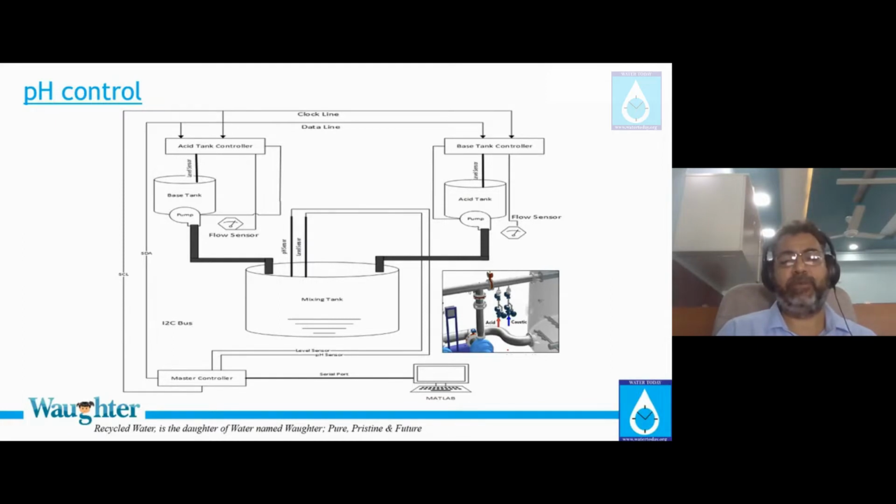You have to take a reading from some point. You have to sense it, and you also have to plot charts. When you are dosing some kind of acid or alkali, how much is the response time for us to get that indication back on my sensor? It is not that you dose it right now and in 3 seconds, whatever pH is coming, you say, oh, that's the right pH. So it takes a little bit of calibration, automation and control in controlling pH. pH is an easy thing to control, but the right device is to have a master controller for the pH.